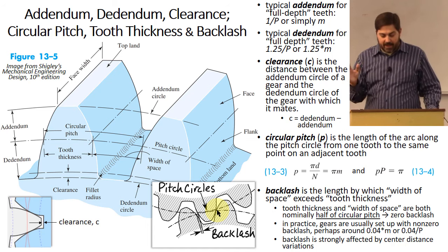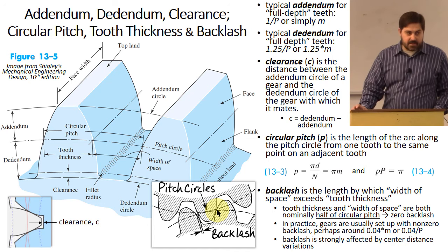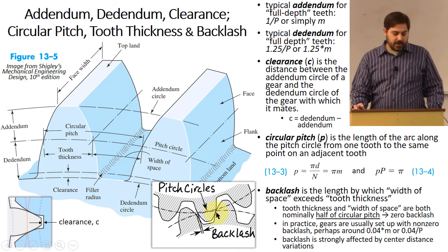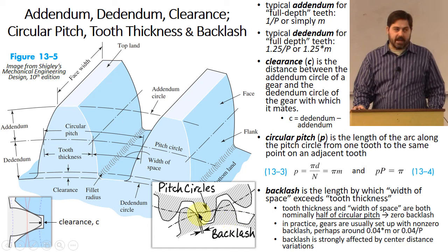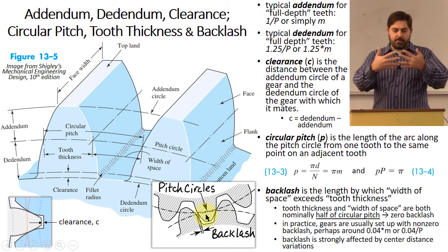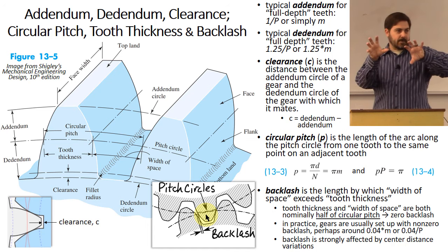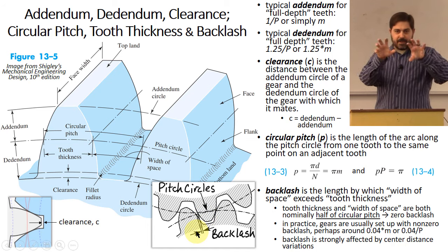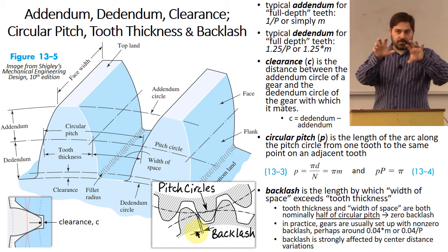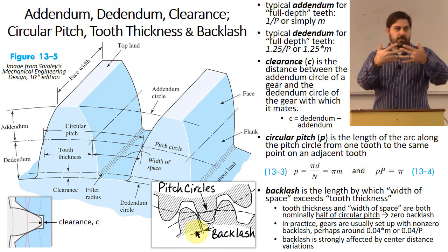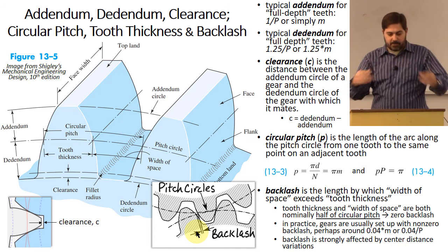Okay, now having said that, if you make these exact, like you actually make them exactly half and exactly half, you could end up with approximately zero backlash, meaning that there's zero amount of space where the two teeth can bounce back and forth, maybe if you reverse your torque bias, right? When you reverse your torque bias, if there's any space in here, you might be able to feel that a little bit in your gear train, because you're shifting from transmitting torque on one face of the teeth over to transmitting torque on the other face of the teeth, right?